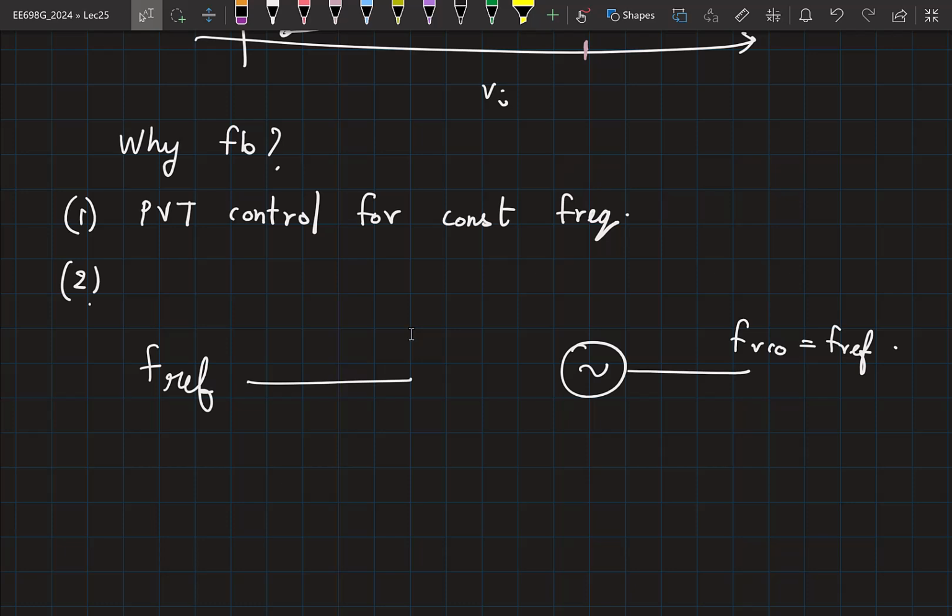We don't put a right, but we are going to put this oscillator in a feedback, right? So when we put the delay line in a feedback, we needed a reference clock. Similarly, here also we will need a reference clock. We are going to lock the VCO frequency to something. So that something is needed. This is going to be VREF, right? Should not FREF. So this is going to be some, let's say, V0 into cos of omega_F t. Right? So it's some voltage domain signal, either a sine wave or a square wave with frequency FREF.